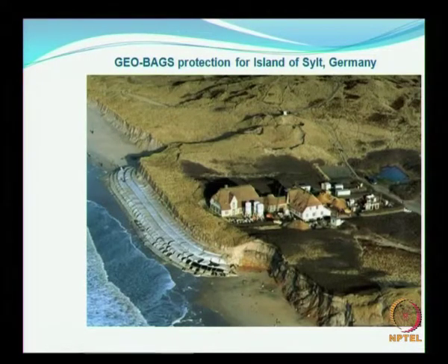So, this is again under the sea wall, wherein they have used what are called geobags, geosynthetic bags. These look like cement bags that we get, filled with sand. They pump in slurry, the mixture of sand and water, the water comes out but the sand is retained, and then it is placed like this.